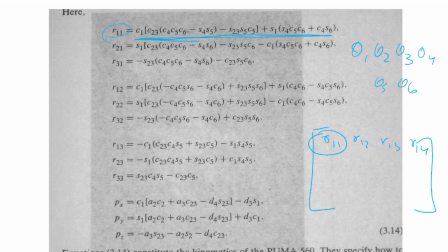Okay. So yesterday when I was talking, I said that for a real manipulator it's not very easy; it's time consuming maybe, and there's a high chance of making a mistake when you're writing out the final matrix with reference to the base frame. So this is what I meant: for a 6 degree of freedom system, there are 6 thetas, and they come in various combinations of sines and cosines. Anyway, we'll come back to this when we talk about the inverse kinematics of the Puma manipulator.